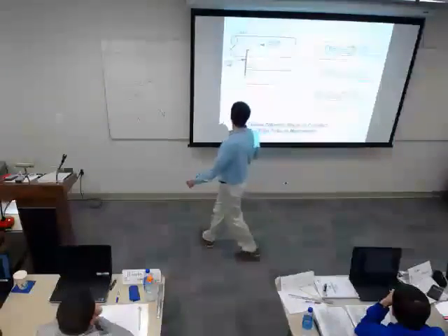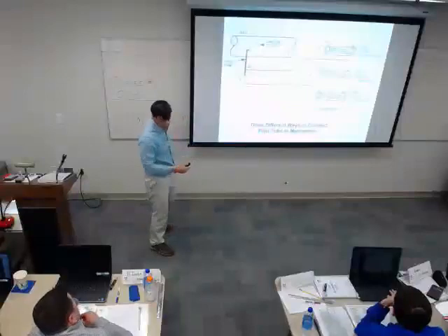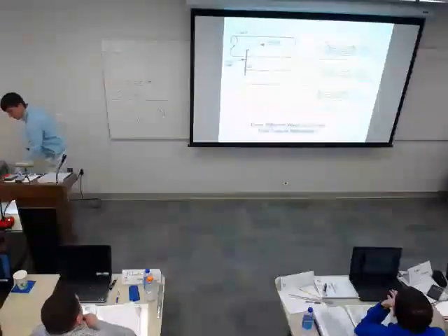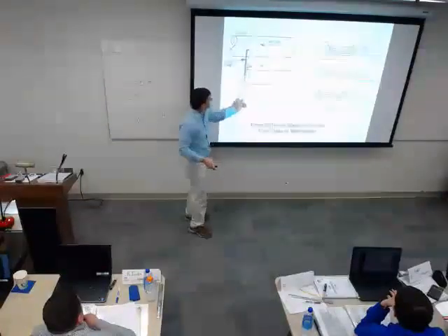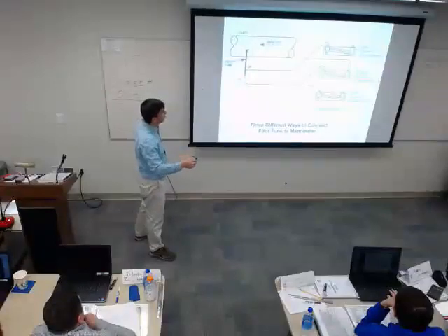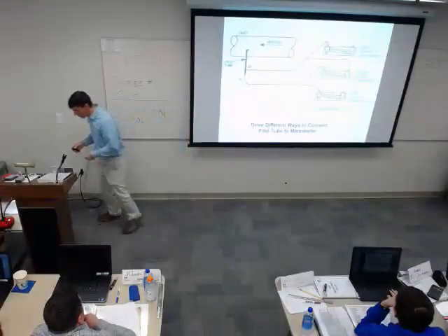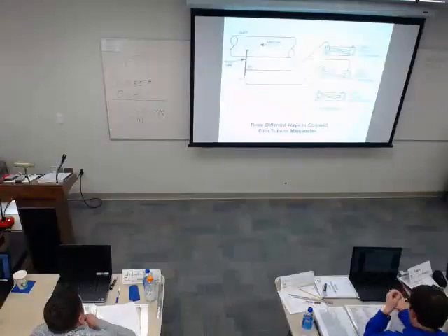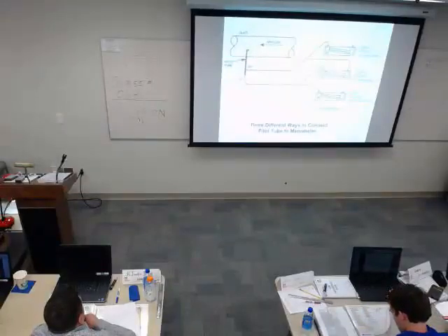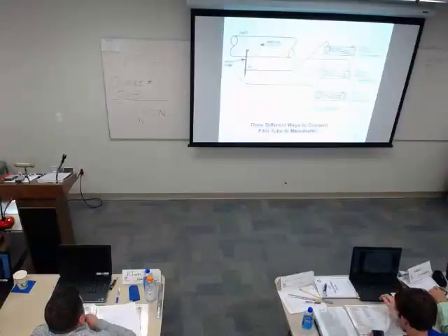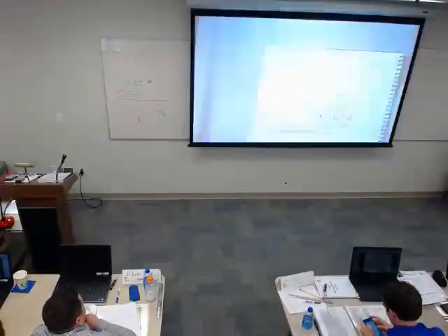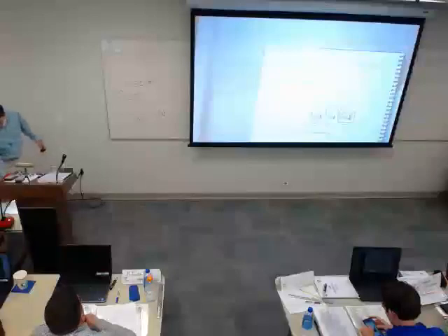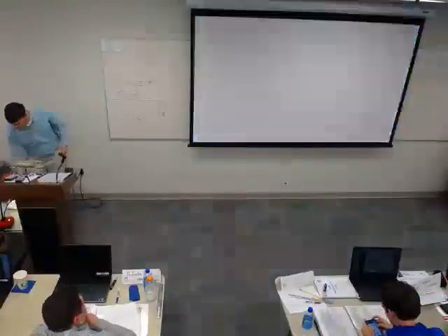And so, depending on what I want to measure, I take my pitot tube, support the nose. The tip has to go in the direction of the airflow. Okay, and if I want to measure static pressure, now this is actually, you know what? This is what I wanted to bring up. Found another chart that they gave us that I think was better than this one. Just a second. This is in one of the books, the same material, just presented a little bit different. This was in the smaller of the two that they gave you, page 26.